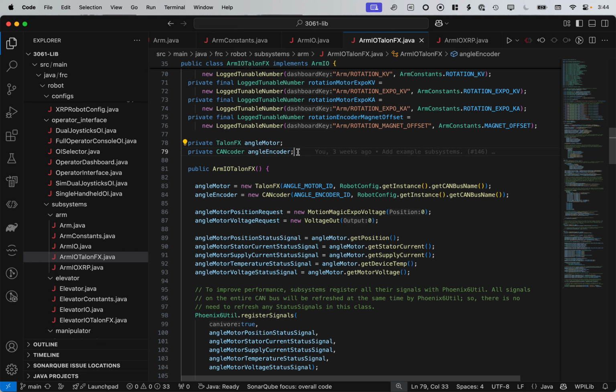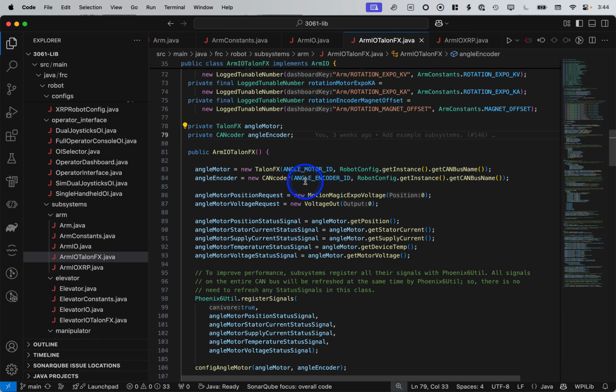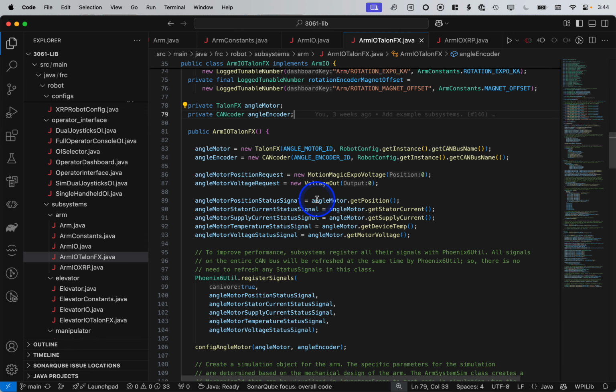As long as the arm is within its range of motion within those 90 degrees or slightly less, wherever the arm happens to be, it will know where it's starting from. In Crescendo, this is very important because we don't want to have complicated field setup procedures. We want to be able to position the shooter where we want it for the initial shot and have it know where it is, without having to worry about making sure things were zeroed properly when the robot was turned on, or some other procedure. So those are some reasons why you might want an external encoder.